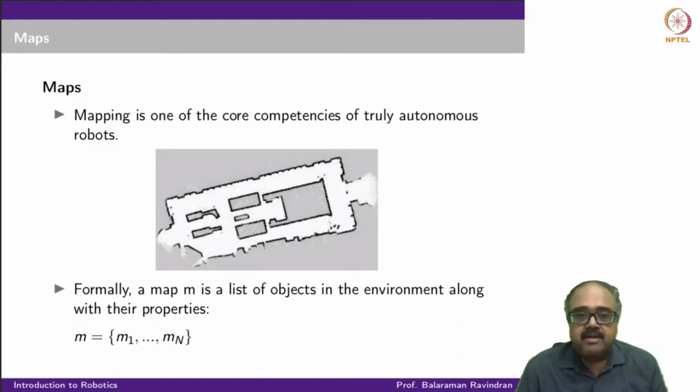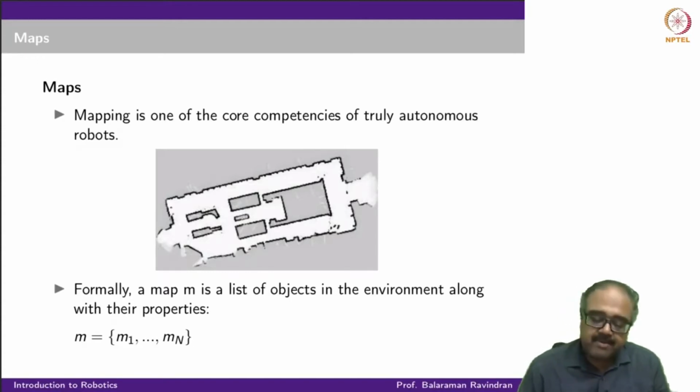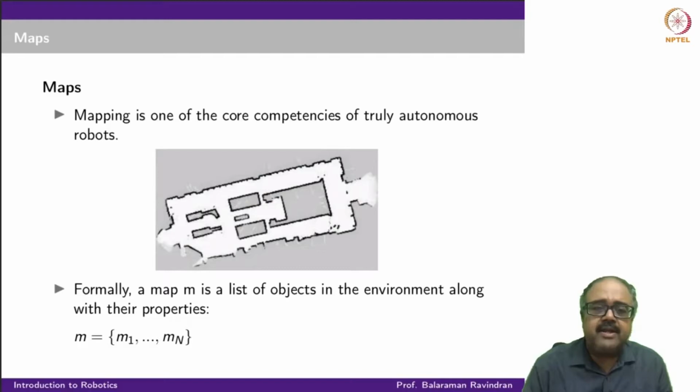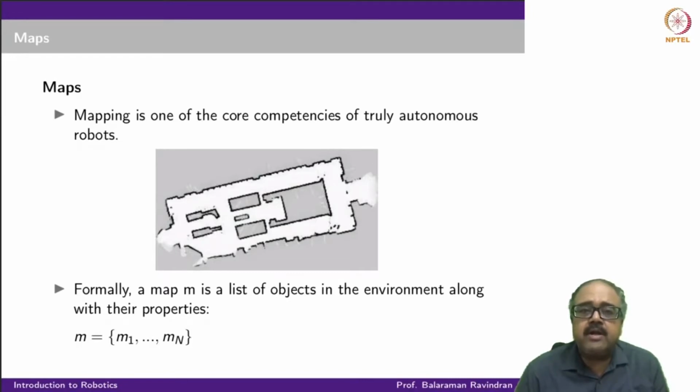In the last lecture, we were talking about how the motion model has to be corrected in the presence of a map. So where does this map come from? You can assume that the map is given to you a priori, but quite often being able to estimate the map of the environment in which you are operating is an ability we want an autonomous robot to have. It's a core competency for autonomous systems, being able to estimate the map of the region in which they are operating.